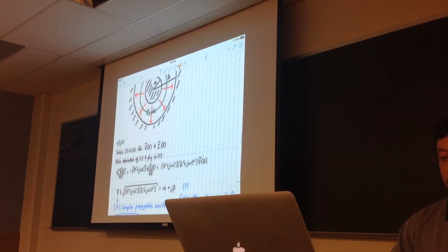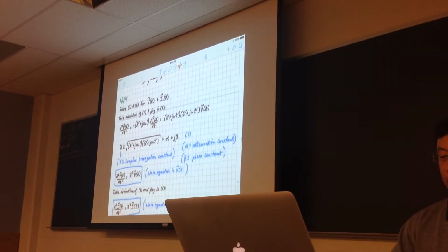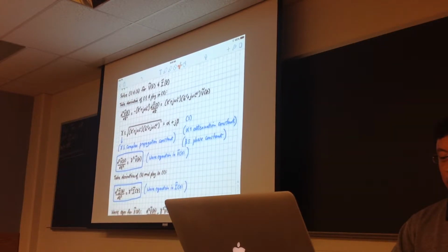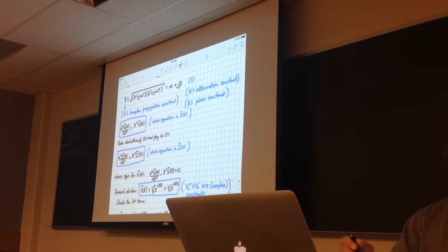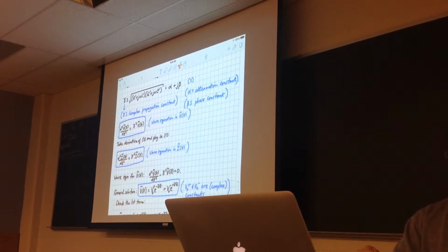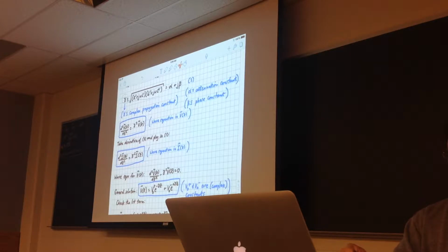And if you do that for, say, the voltage, you get a second order ordinary differential equation in the voltage, and the proportionality constant is this gamma squared, and gamma has your transmission line parameters in it, R prime, L prime, G prime, and C prime. It has your frequency omega in it, 2 pi times the frequency.